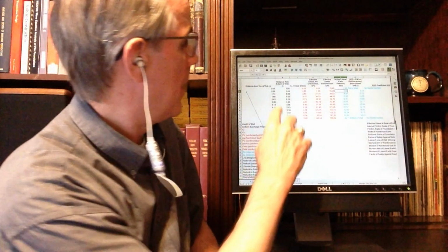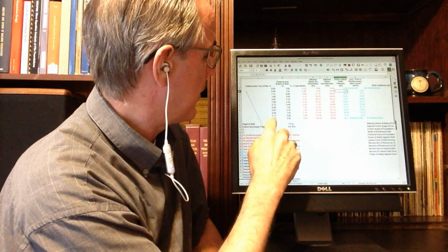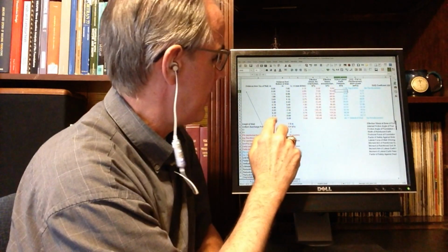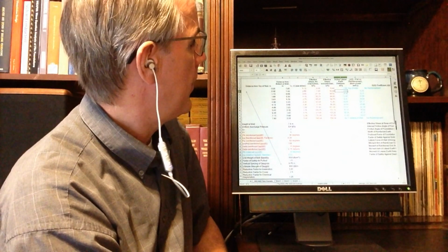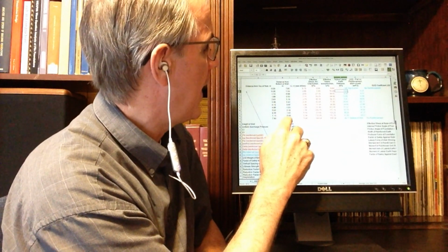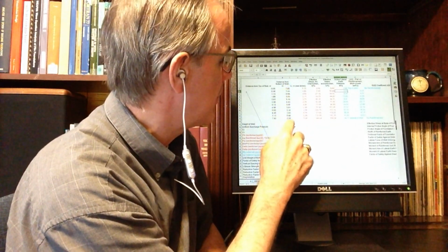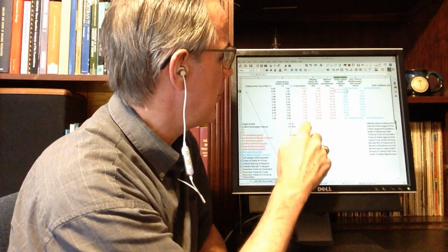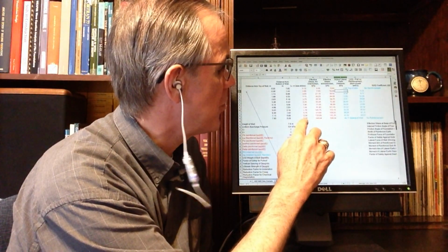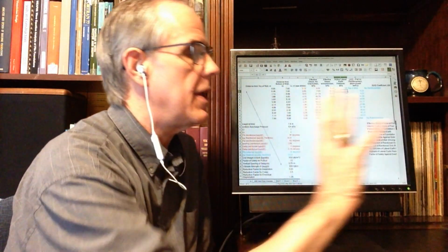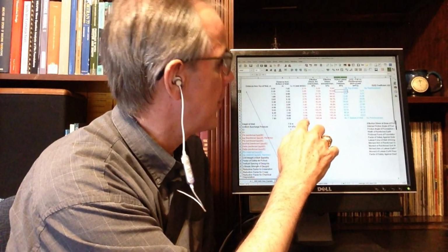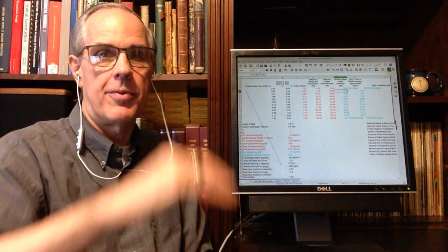The distance from the top of the wall is a function of the geometry. There are 2 points at which there is no reinforcement: 0 at the top and 7.8 at the bottom. The distance from the bottom of the wall is really the reverse of that. The reason I do this is because I use it to compute LR, and I do that using the triangle thing that I mentioned earlier. In other words, the further up you go from the base of the wall, the larger LR becomes. As you can see, it goes from 0 at the bottom to 4.15 at the top surface.